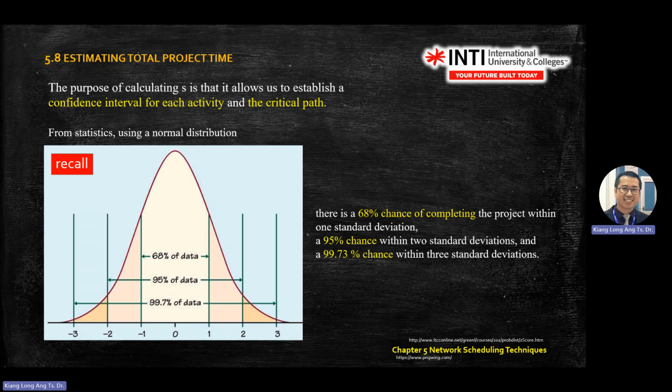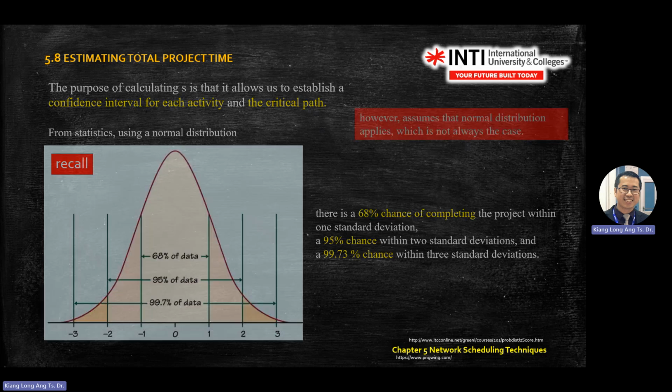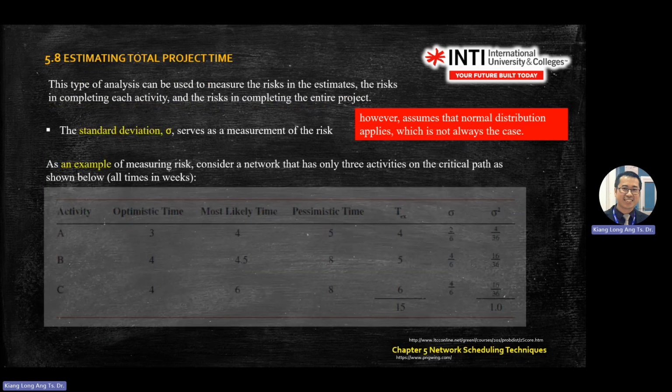The dimension, let's say 5 mm, will be plus minus 0.01 mm, for example. So if you are out of this range, you have failed, the whole lot will be rejected. I'm talking about million pieces. When you produce in the production, you produce minimum 1 million pieces in the industry. So if you're small scale, then maybe smaller volume. So you need to be careful when you have this.